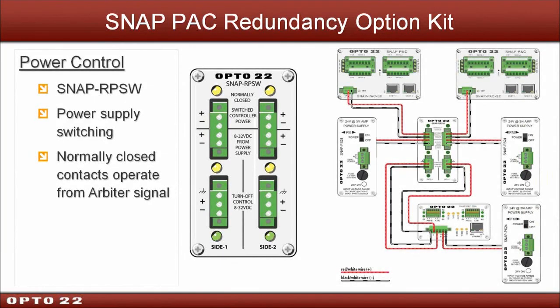It's connected to the arbiter and to both controllers. This switch responds to the supply voltage output from the arbiter, which allows it to reliably restart a controller. So again, this is used to recommission a controller after its firmware has been updated. But it also gives you some other flexibility, for example, remotely rebooting a controller, say through PAC Redundancy Manager.